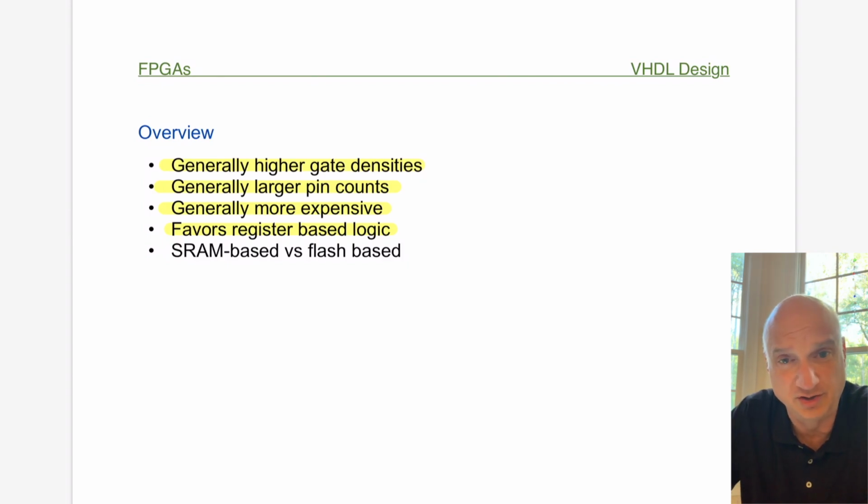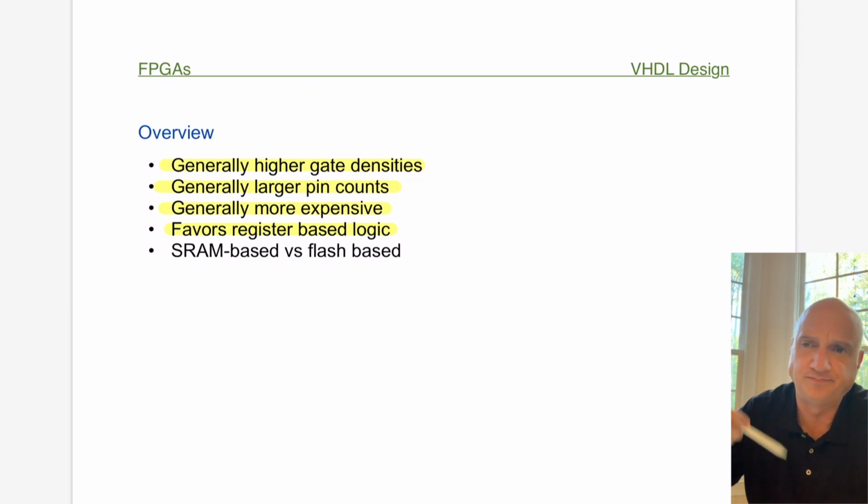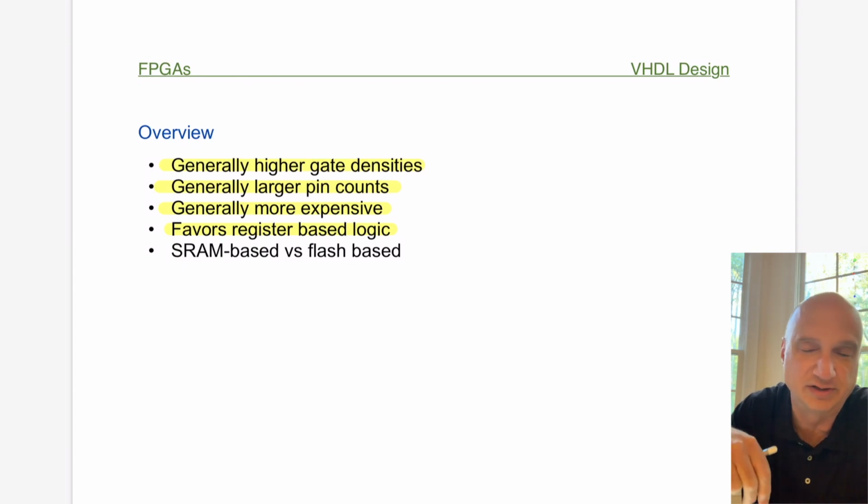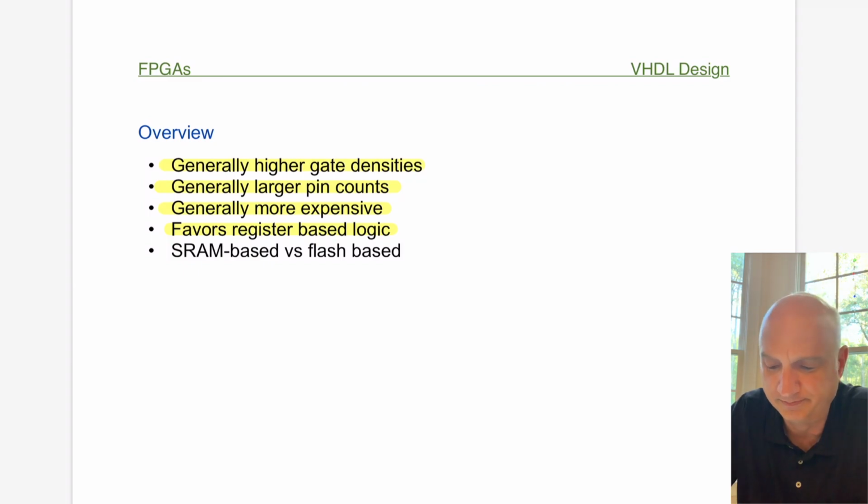So it's not an instant on kind of thing. So you'll sometimes see CPLDs used because they do come on fairly quickly, significantly quicker, because the storage is non-volatile. And so when the power is applied, the design is already there. And so they'll come up to speed pretty quick. An FPGA may take a fraction of a second to get up, or maybe a second to get up, depending on how big it is and how much the configuration data has to be loaded. And so that's a factor sometimes.